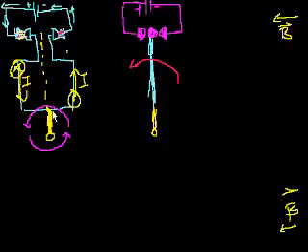Going back to our first video, we have the current going down like this. And then if you use your right-hand rule with the cross product, you know that the net force from the magnetic field is going to be downwards on the left-hand side, upward on the right-hand side. So you have a net torque rotating it like that, rotating the right out of the page, the left into the page or into the video screen, up to the point that you've rotated 90 degrees, and now you're looking